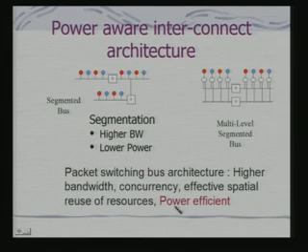These also become power efficient. Why power efficient? Because you are actually making use of the bus much more optimally. If the bus resources are getting used more optimally, your bus traffic is managed better. The moment you manage your bus traffic better, what you have? You have energy efficiency. So, packet switching bus architecture in another way optimizes energy consumption in the interconnect.